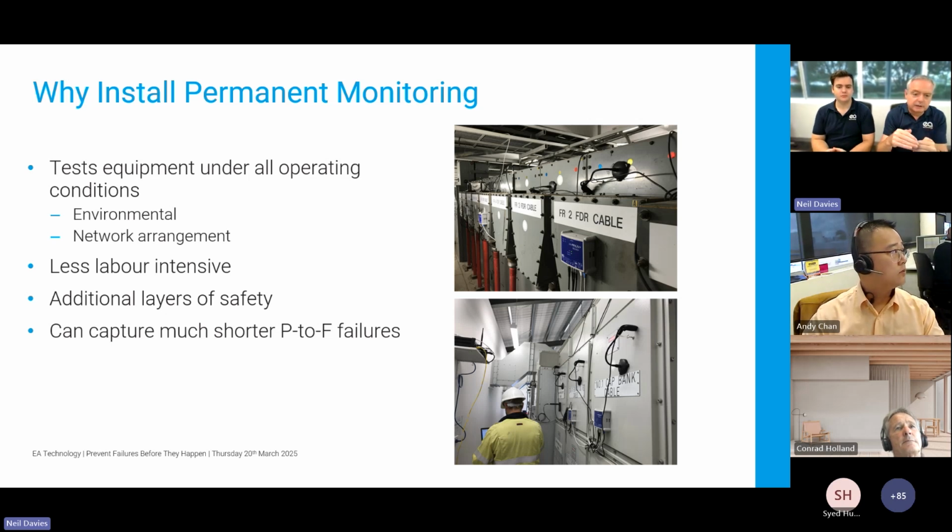So surface discharge is very much driven by obviously defects, but also the level of humidity in the atmosphere. You go and test today and it's quite dry, the sun shines, it's low humidity, then you may not find a problem. You go and test tomorrow when the humidity has come back up, you can see that a discharge is present. So again, operating under all those different conditions.